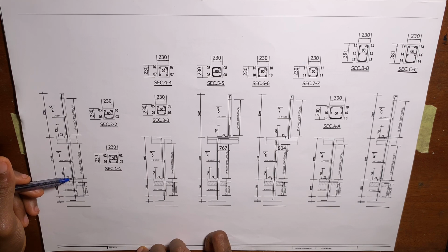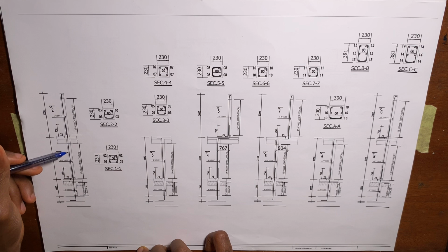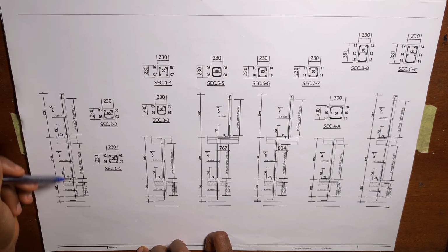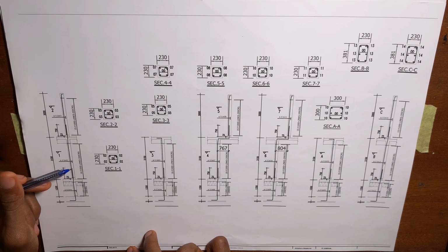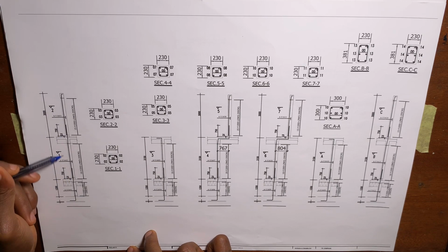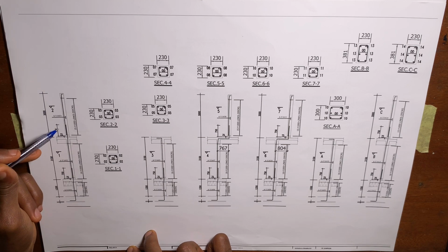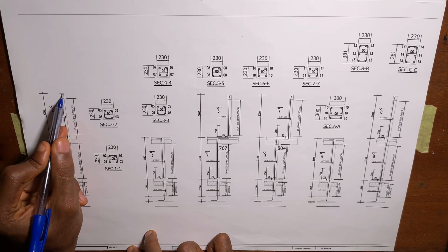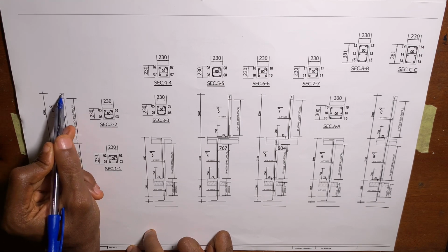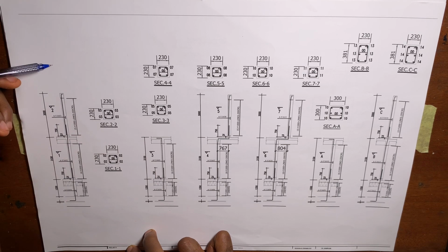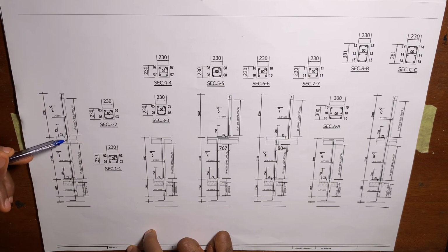You can see another reinforcement now at the side is coming from here and then going up, similarly to how we had in our foundation. So if it is like 5 floors, 6 floors, this is the approach that they use to do the reinforcement for the column. There must be extra for the attachment of the reinforcement for the next floor. I hope you understand. Now you see that the drawing that we're using is just 1 floor. You see that it ended here. It did not go up again, just like you can see in the previous one.